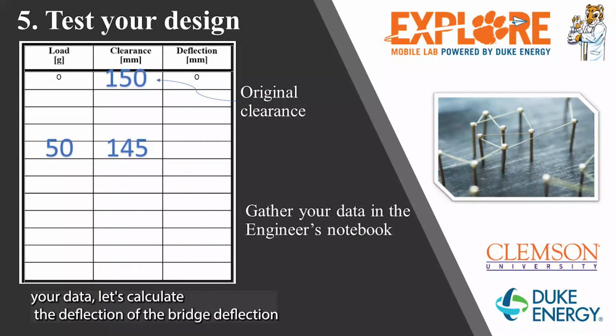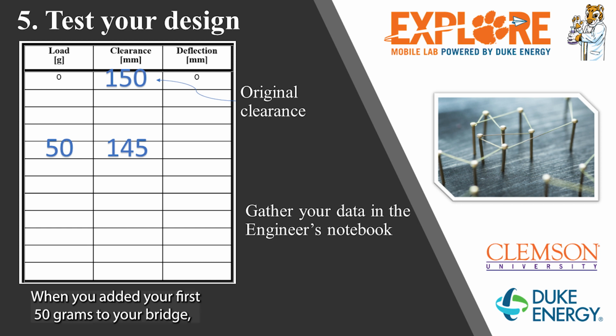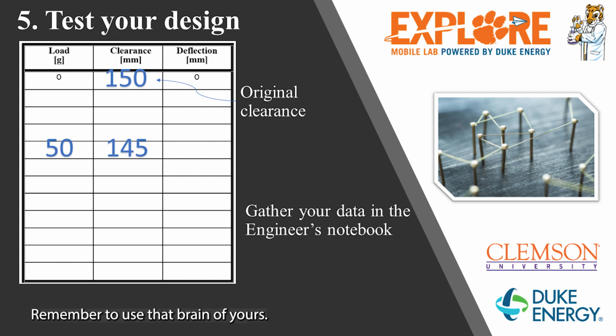Now that you have your data, let's calculate the deflection of the bridge. Deflection is the original clearance distance minus the newly measured distance. When you added your first 50 grams to your bridge, if your clearance was 145 millimeters and your original clearance was 150 millimeters, your deflection is 5 millimeters. Pause the video now to work on completing the table with the rest of the deflection measurements. Remember to use that brain of yours.